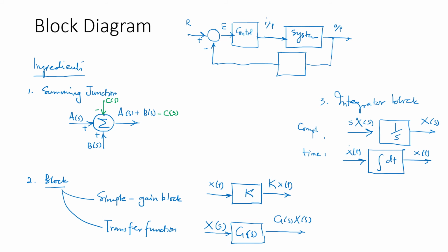And that's why this graphical approach is going to be much more helpful in control system designs. Oftentimes, it becomes difficult to construct a system's transfer function using block diagrams. So it would generally be advisable to construct a signal flow graph first, and that is another representation scheme. In that case, you have nodes, and these nodes are connected with each other using signal flows.